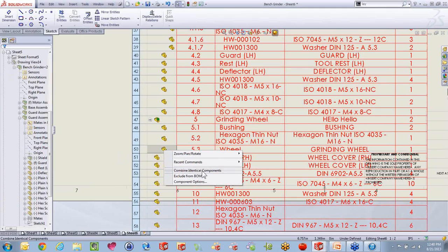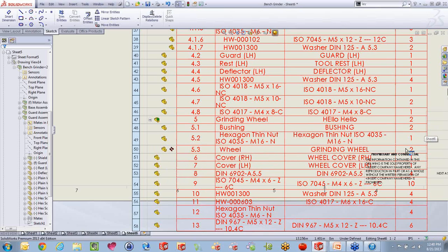If I select that one, SolidWorks kind of forgets about the sub-assembly here, but goes in and finds all identical components. So when I hit that, you will see that it now displays the right amount it needs in here. And it will show that with a little icon over here, that it now is actually showing everything that is true to our model.